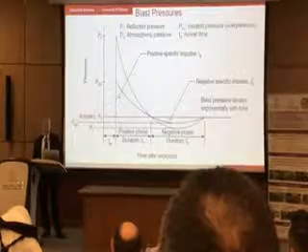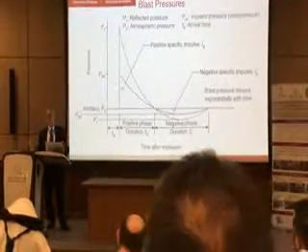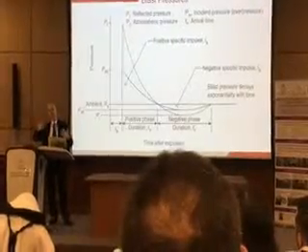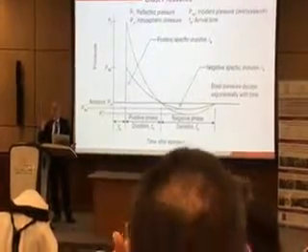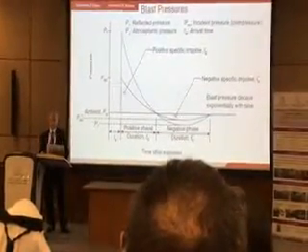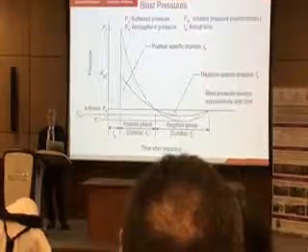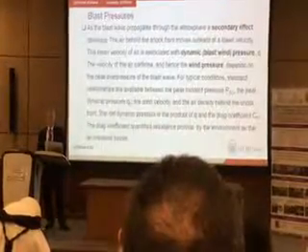And then there's the positive phase, which is what we usually deal with. And then after the pressure is gone, there's negative pressure behind the shock wave. There's a vacuum, and it starts pulling the building back. But this is so small, this is called the negative phase. In design problems, we usually ignore that.